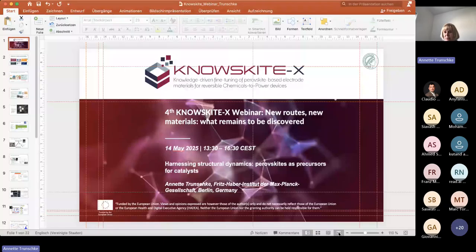The lanthanum manganese oxide we also prepared by hydrothermal synthesis, but I would like to focus on the combustion synthesis material, lanthanum manganese oxide and samarium manganese oxide. The 2 materials have different surface areas. The lanthanum has a higher surface area and the more active samarium manganese oxide a lower surface area. And the structure is also different. We have rhombohedral structure and orthorhombic structure.